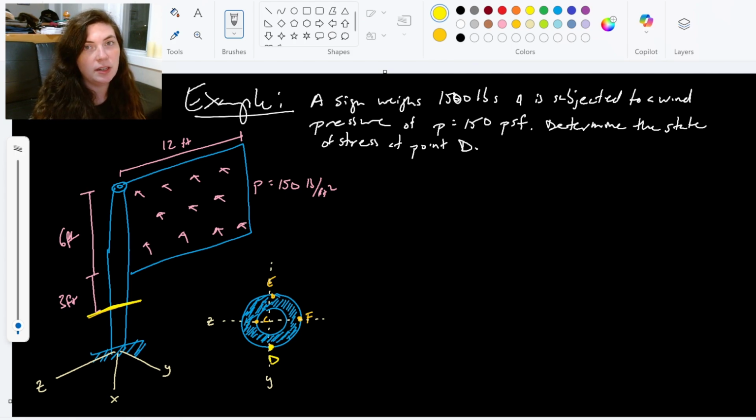And the first thing that we're going to need to do is, of course, some statics. Thankfully, we don't need to actually find these reactions down here, because I can draw a free body diagram for this top portion, simplified into my little flag sign and my cut, the section of interest. I can simplify this pressure, pounds per square foot, by multiplying by the area of this sign.